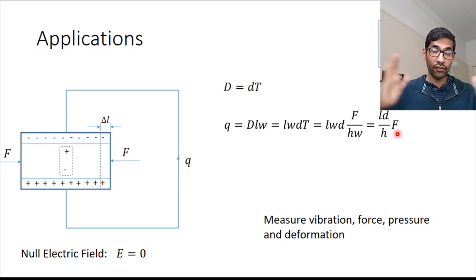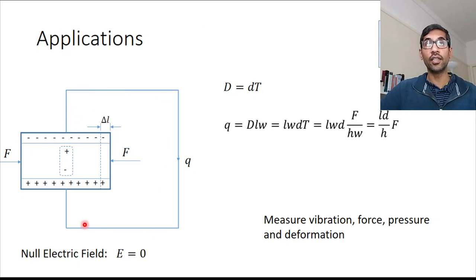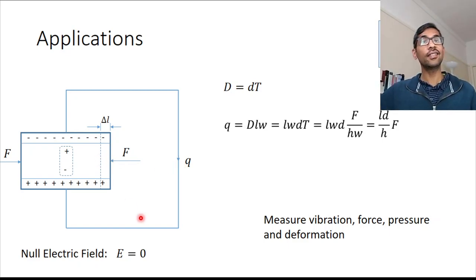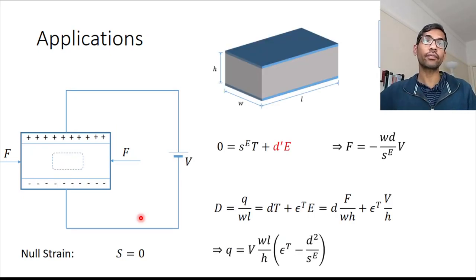So when you are applying a force on the crystal and you just put a short circuit here, and if you can measure this current, this charge that is flowing here, that gives you an estimation of the force that is being applied on the crystal. And this is the way we can use piezoelectric crystals to measure vibration, force, pressure, or deformation, right? Is that all right? So that's the second application. Let's look at another application.